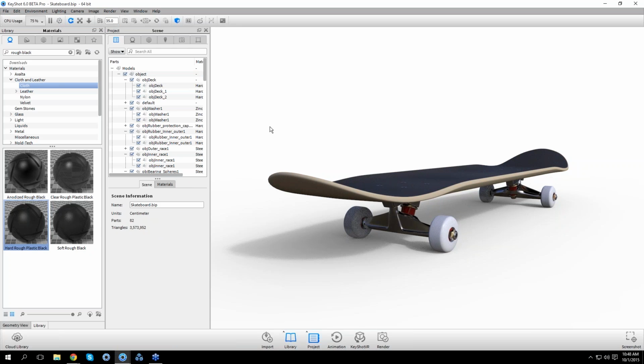Yes, that's correct. So the question was, does the split object surfaces work with NURBS models? And the answer is no. If you do have an object that includes NURBS, then the objects or the surfaces that you split will still be there when you're not in NURBS mode.